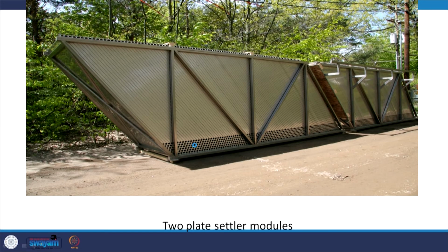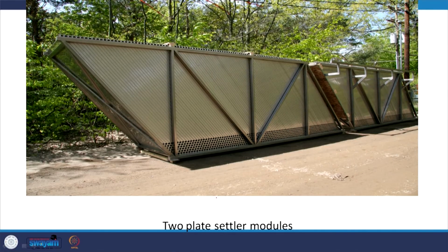So there are other kinds of settling basins, but where I guess the design is a crucial aspect. We know that you don't really require a lot of depth if you design it right. But typically to provide for flock formation and to have your sludge settle down well, you sometimes provide depth as high as 3 meters. But theoretically, if you look at sedimentation, you don't need to do that. So the way to do it is to provide more surface area, and bring down the V naught, by providing these plate settlers or tube settlers.